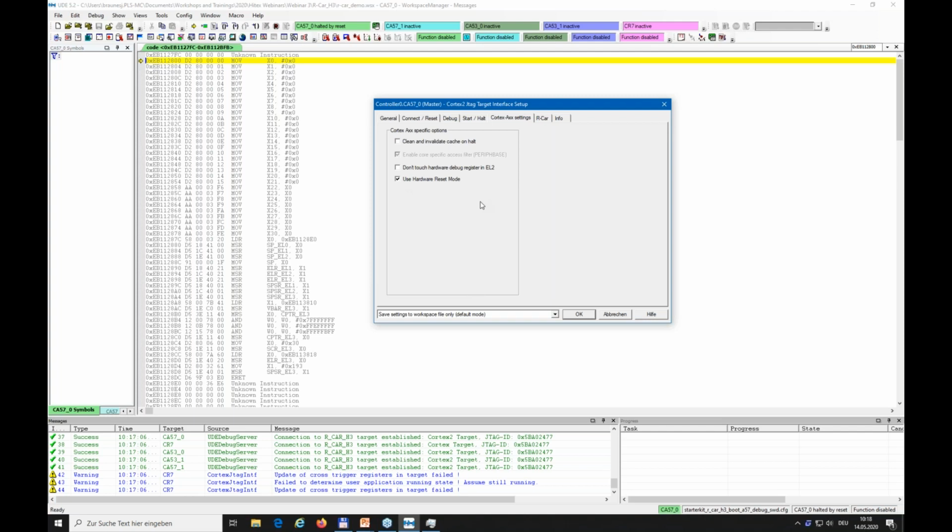That means that the target is set to the reset vector address after the reset, and from there a boot ROM code is executed, which then calls a boot header application located in the RAM, and this boot header application is copying the actual Multicore application from the external flash memory to the internal RAM. Okay.